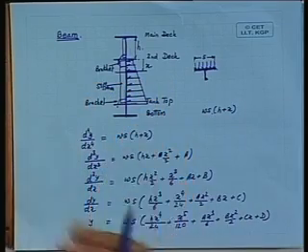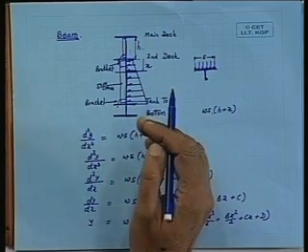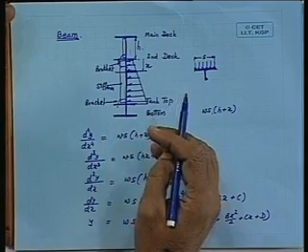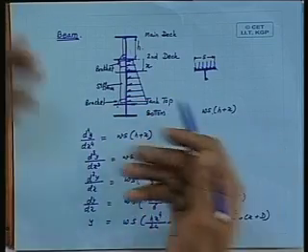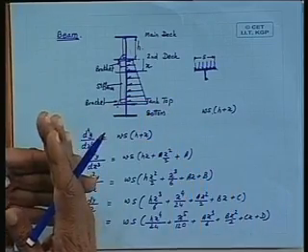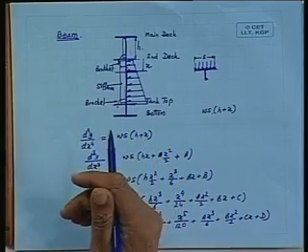but one thing we should not forget, that this tank top is again made of thin plates, thin structure. The second deck is also a stiffened plate structure. So, basically the plate to plate contact is a thin plate made of more or less the same material, normally the same material, mild steel. It is possessing the same elasticity.